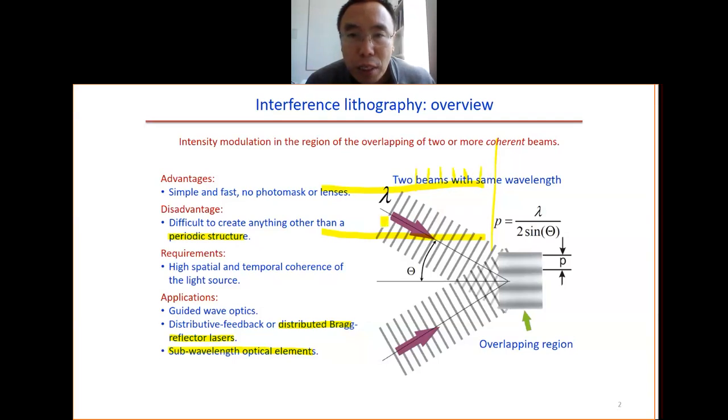When we pattern the gratings, the light can also be reflected. How come? You can imagine the light coming in. It can feel the lines on the surface of the waveguide because of the evanescent wave. So there will be some reflection coming back. Then, going on, there will be more reflection at the second line, and some reflection on the third line. They go back like this all the way. The requirement is that when the reflected light is in phase, it will interfere constructively.